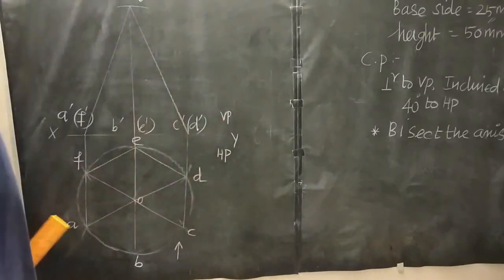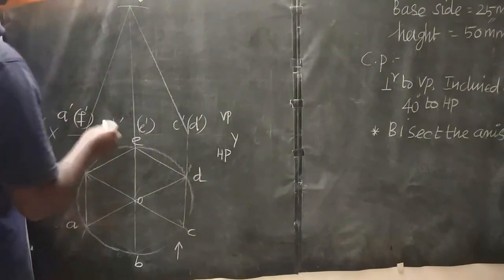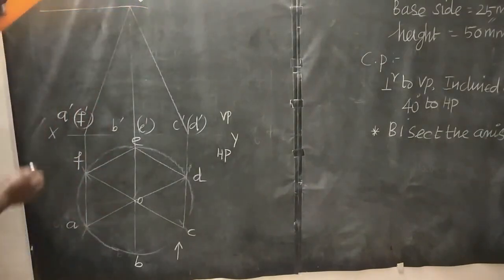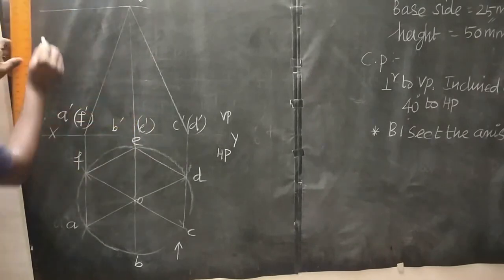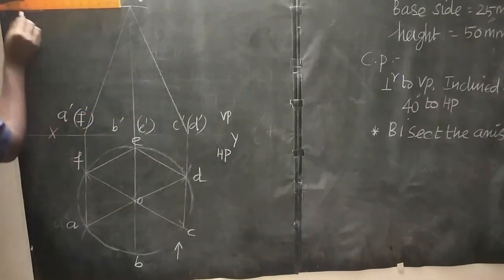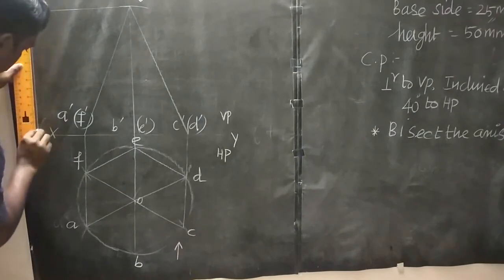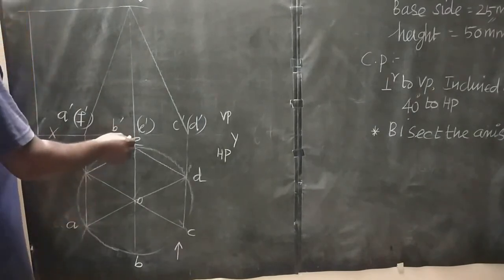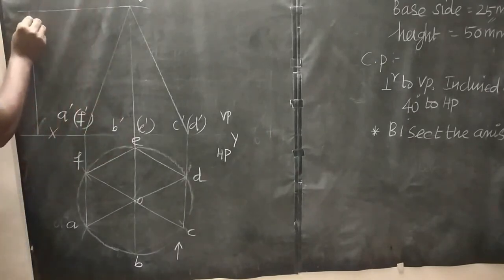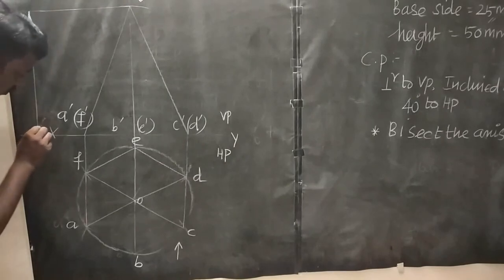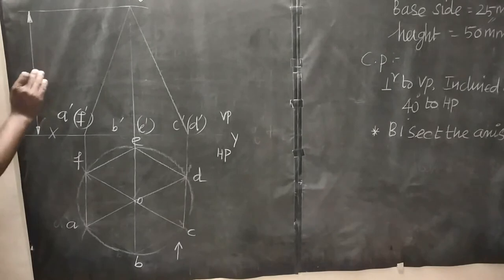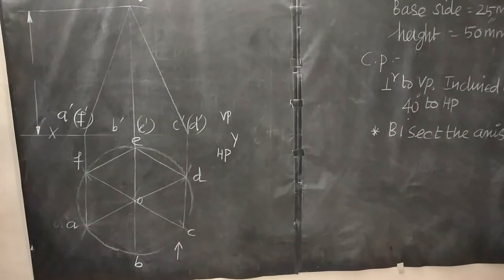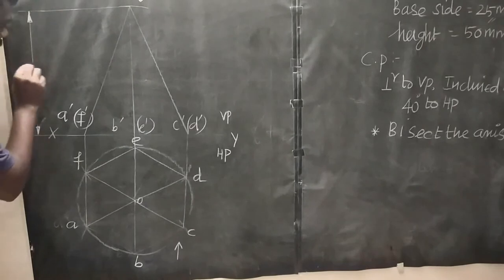Okay, then define the dimension. So here draw an extension line, then extend this XY line, then here draw the dimension line. Your dimension line should be parallel to line B dash O dash. Then after drawing this dimension line, draw the arrow at its end. Then take the middle part of this dimension line, erase this small segment, then enter your dimension value in this space. What is the height here? 50 mm. So just write 50 mm.